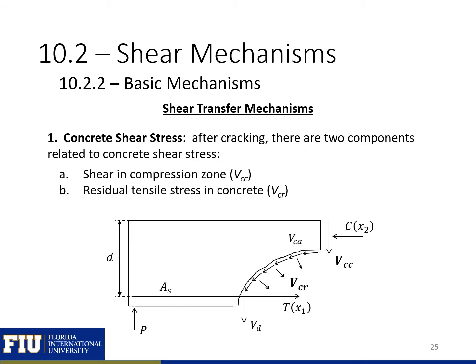After cracking of the concrete in shear, there are two components related to concrete shear stress. There will be some shear stresses carried by the uncracked concrete in the compression zone, labeled VCC here, so the uncracked compression zone here. There are also some residual tensile stresses carried by the cracked concrete, labeled V sub CR here.